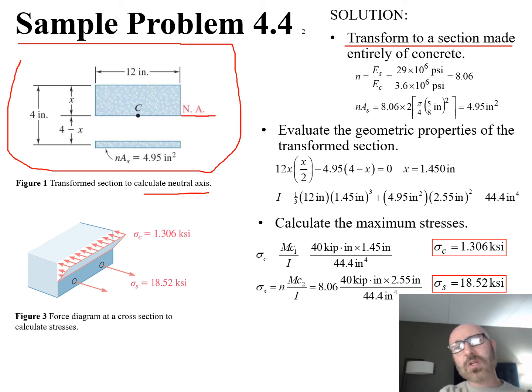The way that we're going to visualize this in this figure, we're really going to have 2 of those rebar in this rather than all 5 of them for this example of how to solve this. With 2 of those, there's 6 inches on center. So if there's 6 inches on center away from each other, therefore, if we have 2 of those, it's going to be a total of 12 inches of width as we look at those 2 pieces of rebar.